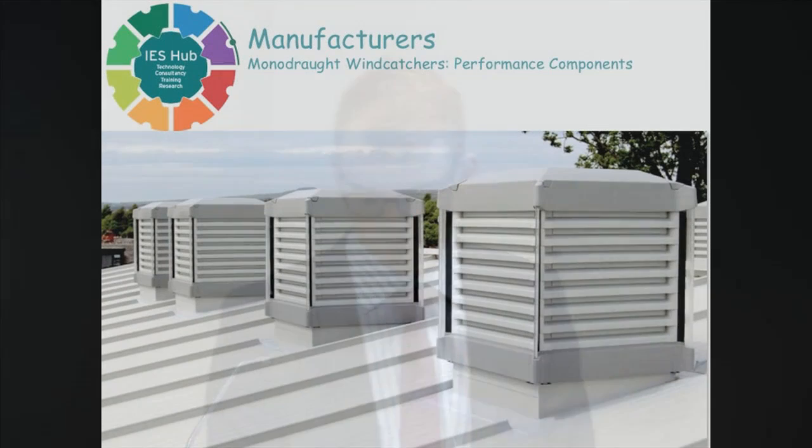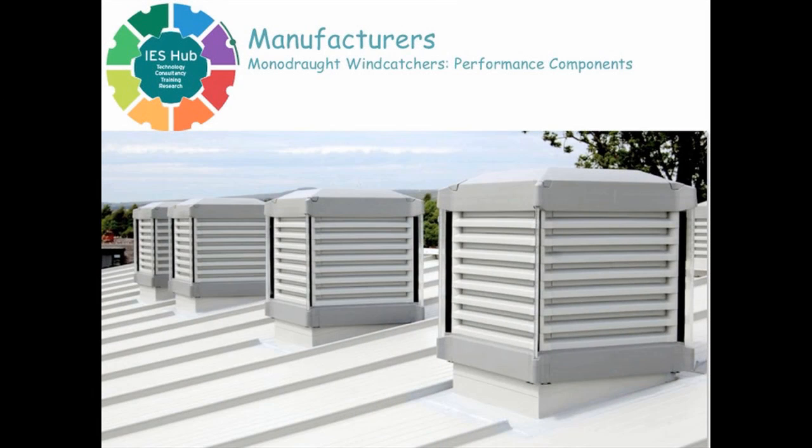Now the quadrants that are downwind of that prevailing wind experience a negative pressure region as a result of the flow separation around the unit, meaning that the stale warm air that's built up inside the room which the unit is serving is naturally drawn up and out and released, so you get a continuous air change rate. The reason I've shown this to you now is because when I do a quick live demo of the new feature, we can actually see the way that IES mimics this performance through the bulk airflow analysis. And that's just a quick image of our systems in an actual live installation.